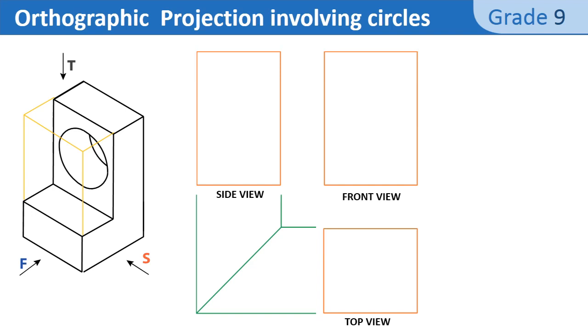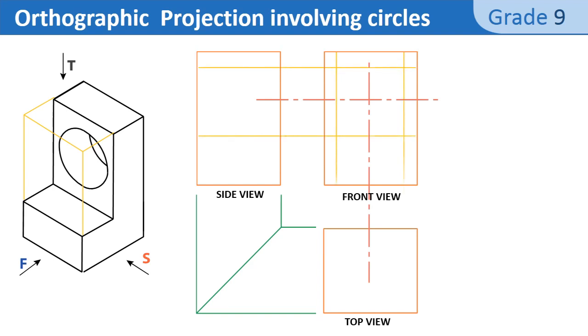You have to measure the dimensions needed, that is the circular diameter, etc. So when drawing the projection lines, you have to draw them in such a way that they reach the side view and the top view. Then you draw the outline forming the front view.